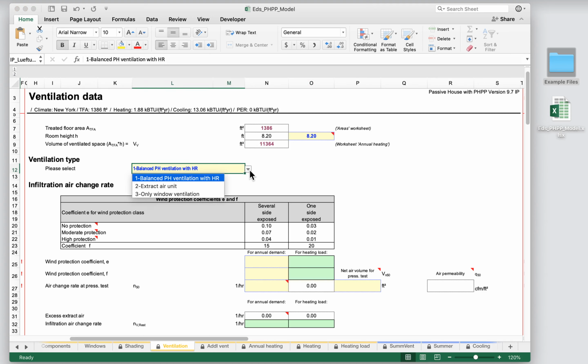So when it comes to Passive House buildings, the requirement for a Passive House certified building is that you provide adequate or appropriate fresh air ventilation, healthy and comfortable interior spaces, and that you meet the energy performance thresholds. There is no specific requirement when it comes to new construction typical certification that you have a specific type of ventilation system.